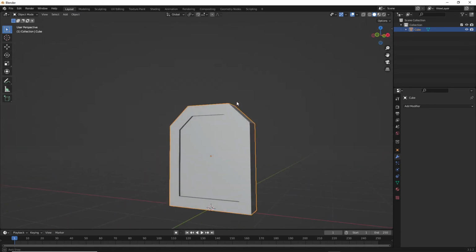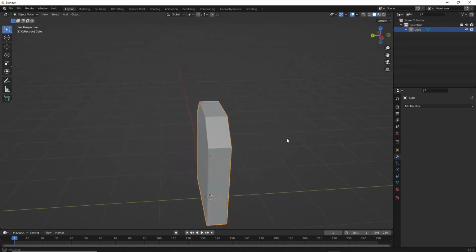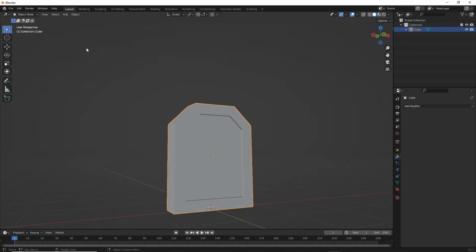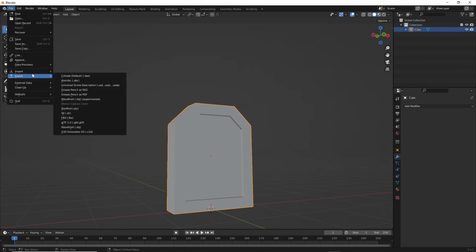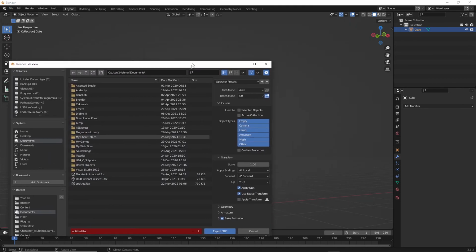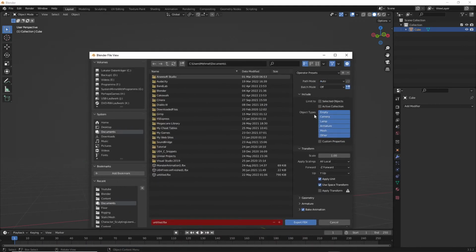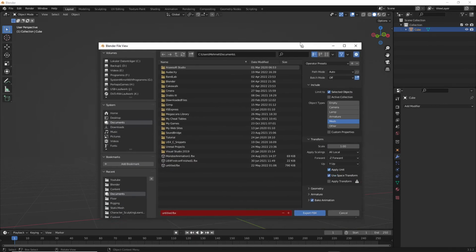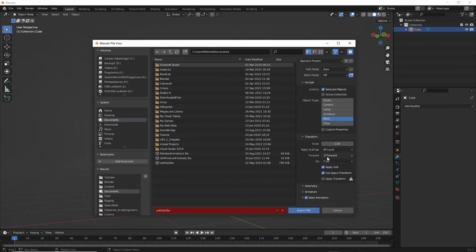Creating materials, so I just add another material in Unreal Engine. Let's export it. So let's go here to export as an FBX file, and let's do the same thing we did last time. It worked fine, which means I set the selected object. It is just a mesh, and I have selected it here on the right side. I can see it, it's selected. That's good. Then I go down.